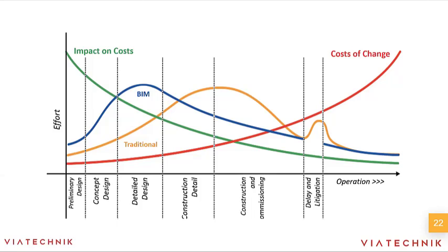Early commitment to the use of mass timber by everyone on the team is super important to successfully develop a project. Let's remember that mass timber is not simply a material substitution. It's also a system that requires a holistic approach that everyone needs to be committed to from the start.